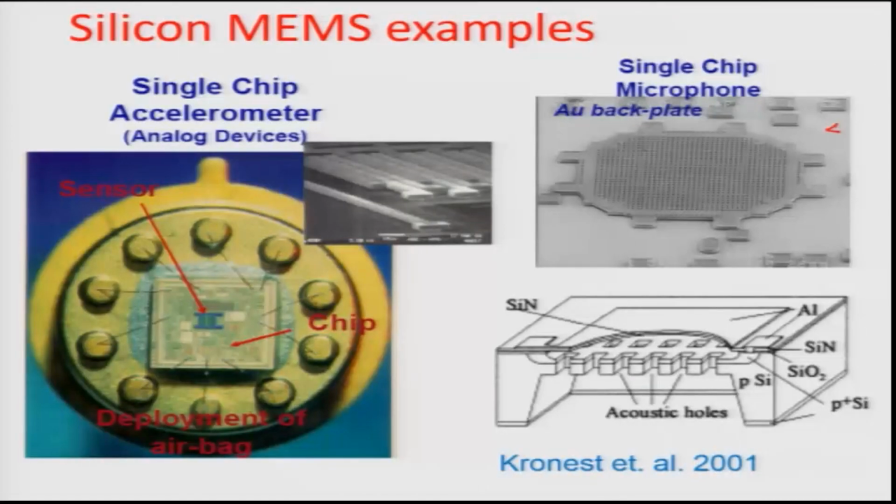There are a couple of other examples which I would like to show. These again are single chip microphones based on a small perforated film which has a piezo layer, and there are acoustic holes on this film because of the perforation, and so whenever there is a sound wave which strikes the structure from one side, there is a response in terms of an electrical signal which happens and which relates to the transducing of the acoustic waves into electrical signals.